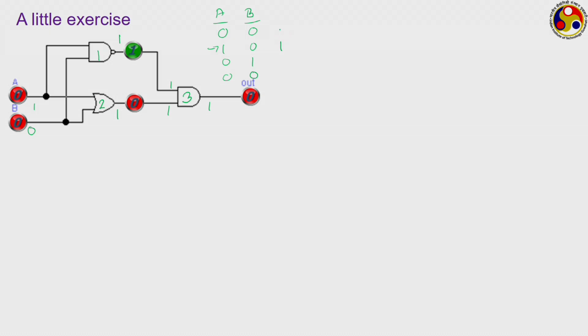We can write the first one, which is already shown, that is a 0. What will be the results if we change our input to, let us say, 0 for A and 1 for B? Then again they are going to a NAND gate, so quite similar to the previous situation, the output will be 1, similarly for the OR gate it will be 1, and finally we are going to get another 1 here.